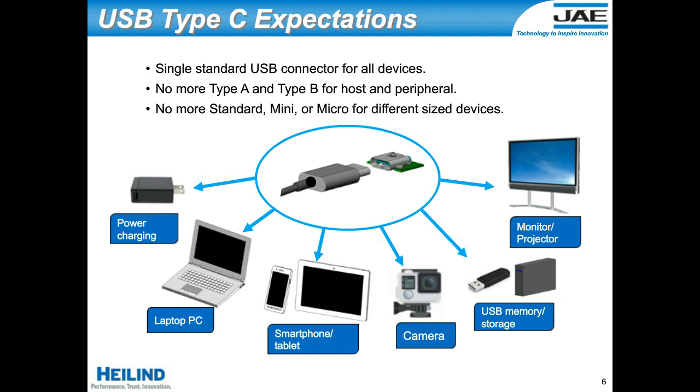Also, with the introduction of the USB 3.0 standard, the cables were no longer backwards compatible at that point. Basically, the actual plug connector shape changed in order to add in these SuperSpeed pins that were required for USB 3.0. So that means that you could no longer use a 3.0 cable and plug it into slower or legacy type USB devices anymore. So again, the requirement to have a bunch of different types of cables for each user.